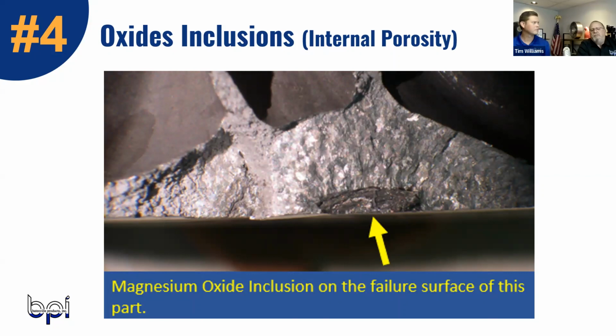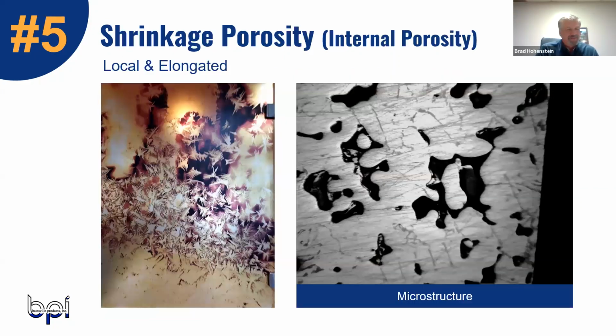We've also had points where you choke it too much and spray the metal in and erode the core or the other side of the casting. It doesn't sound like something you want. Nope. Spraying is never good. Well, that's that local oxides or dross you see on the surface when you do that.